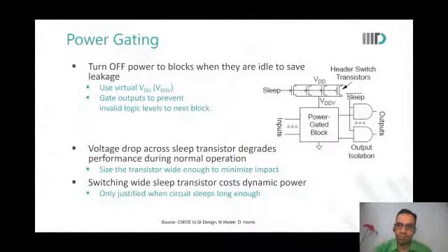So gate leakage will still be there, and that much the MOSFET cannot control. Full memory inputs are just going to gates. There may be 20 inputs in a memory. So even in this entire block, only the first stage of this block will be leaking from the gate. The rest of the inputs will float in between, okay, yes.